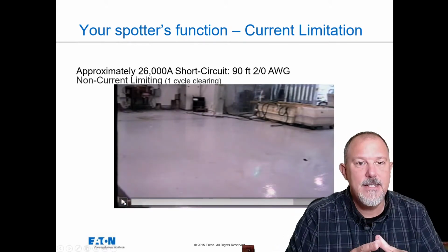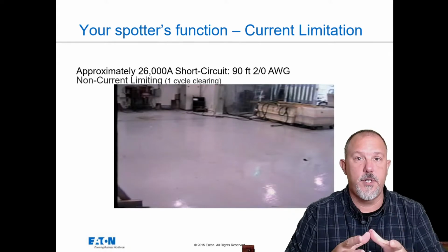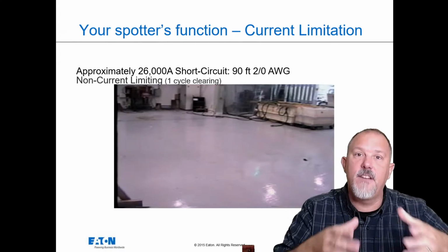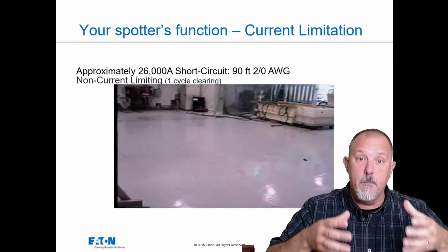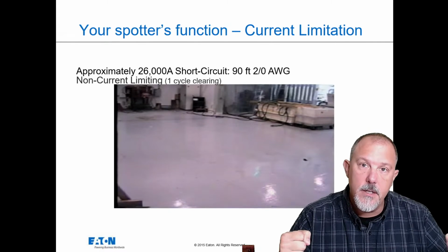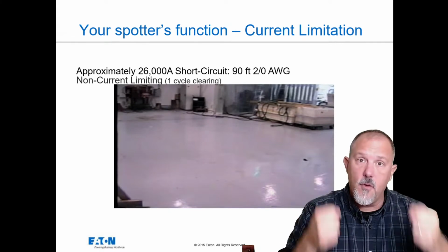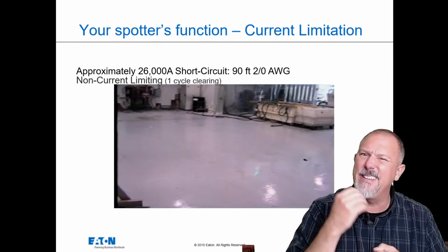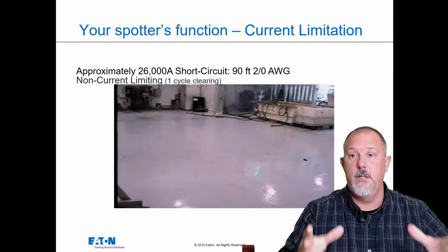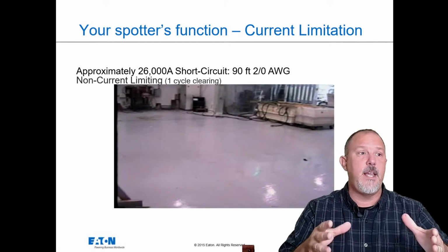Now that is a lot of destructive forces. That shows you the magnetic forces that are being imposed on those conductors. They want to separate. And from a performance perspective of equipment, we've got to consider that, especially on some of these large breakers where I can let the fault current flow for, say, 30 cycles.